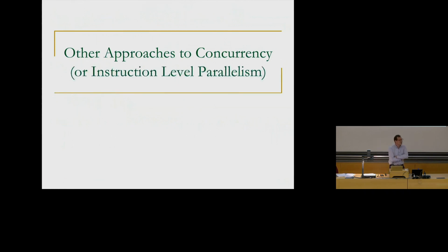Any questions? Is this clear? The complexity? I'm not going to ask you questions on the load store forwarding logic. But you should really know that this is really the tough part. People try to scale the size of the instruction window. Yeah, they can scale the reservation stations, but it's very tough to scale this logic much larger. I believe existing processors maybe have a 24-entry store buffer, even though the instruction window size may be 256 or so. So it's very small compared to other parts of the machine, and you're usually limited by how many stores you can put into the machine because of that reason.